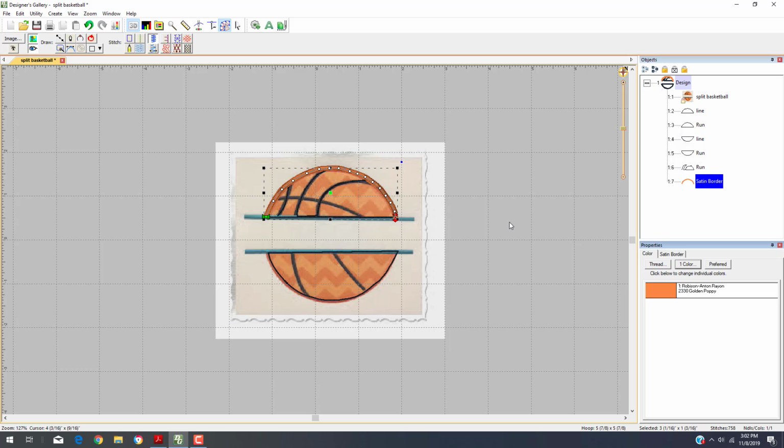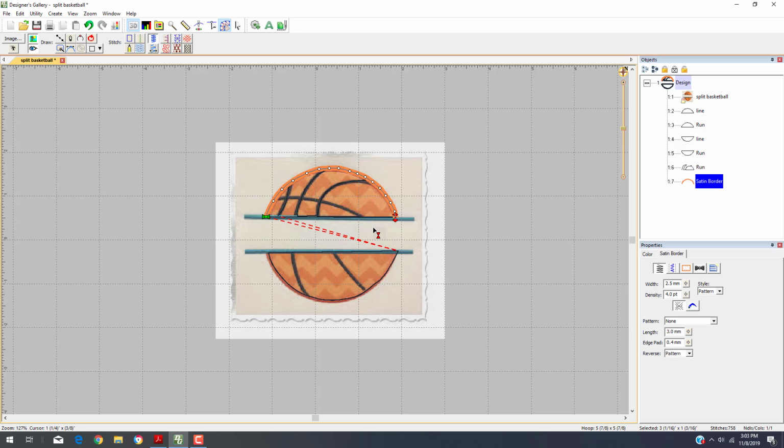That's a little better. And then say OK. So this line up here is exactly the same as the one on the bottom. So in a minute, I'll be able to get right to that without causing myself to have to redo it. But what I want to look at is my start and stop on that. So I'm going to click it. You see the green and the red bow tie? So this is where I want to start to digitize on this half, or I can move my stop wherever I want.